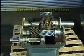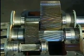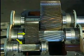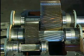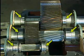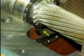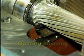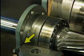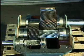This gearbox is a double reduction type. It steps down the motor speed in two stages. The first stage of speed reduction occurs across this helical pinion and gear. The second stage of reduction occurs across this pinion and gear. The pinions and gears are mounted on shafts, which are supported by bearings on either end. The bearings are supported in parts of the casing referred to as the bearing housings. Spacers, or shims, are placed between the bearing housings and the end caps to properly position the bearings, shafts, and gears inside the casing halves.